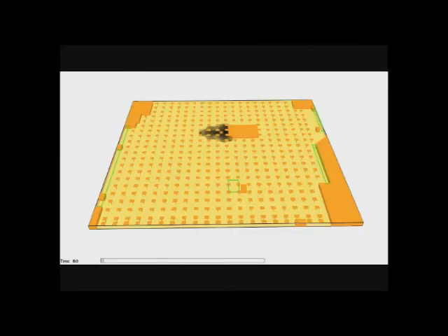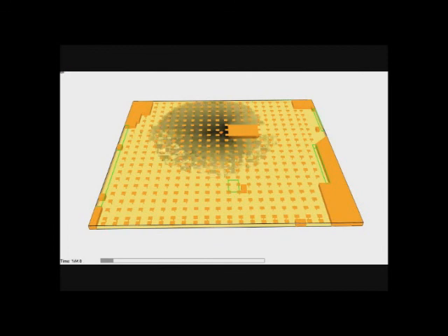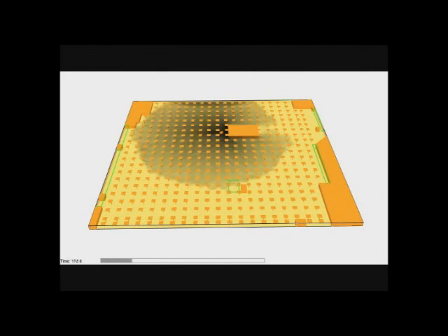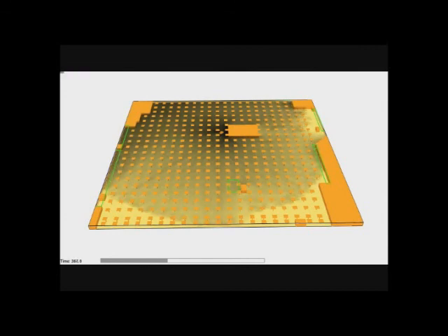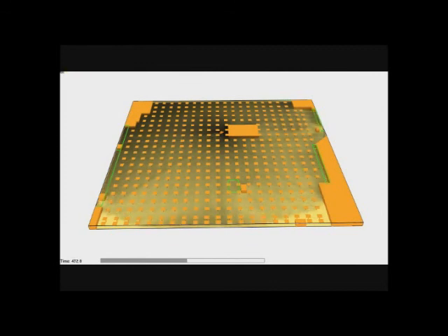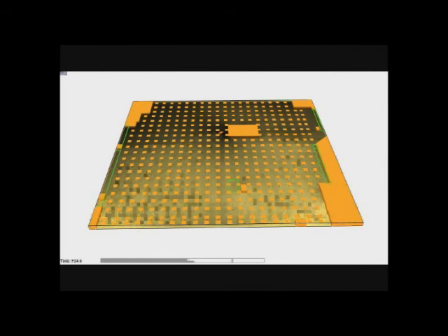In this simulation, you can see how the smoke is spreading in the complete basement. Although visibility is maintained here, in about 200 to 300 seconds the complete area is filled with smoke. I think this can be very well directed to constrain the smoke in a particular zone using mechanical ventilation. We can do that. We are right now working on designing the system so that we can keep it in a particular direction using just natural ventilation and jet fans.